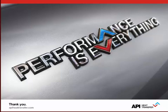Sure. The easy answer there is you're going to over-design the heat exchanger in terms of excess surface, so you're going to make it larger and more expensive than it needs to be if you're too conservative with your fouling factor. The other thing is, in the initial clean stage, it's going to significantly overperform what the heat exchanger was rated for in the fouling condition. So your temperatures will be either hotter or colder than you initially planned because the heat exchanger is clean in the beginning. So you have to have a means of compensating for that in your process.